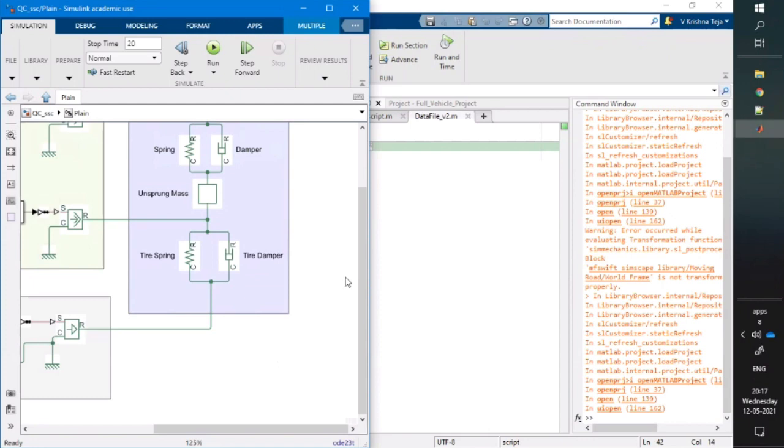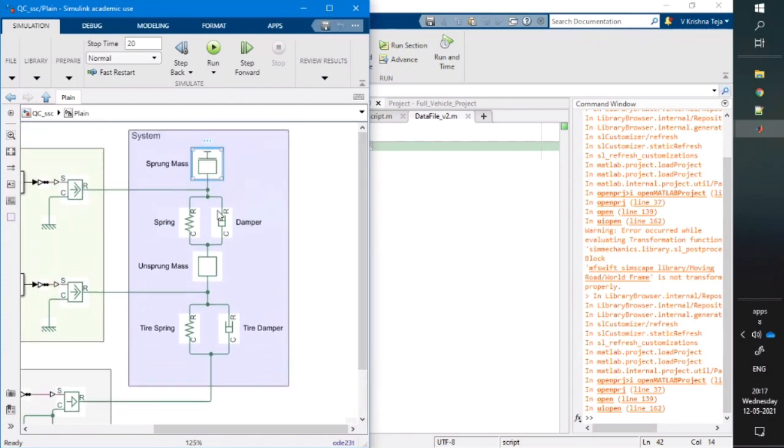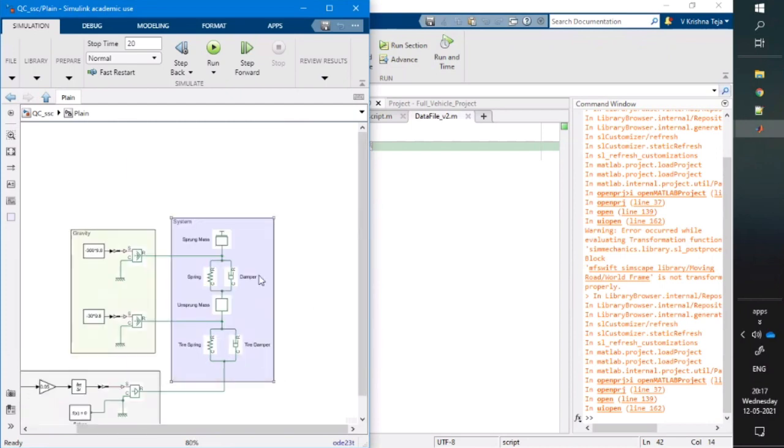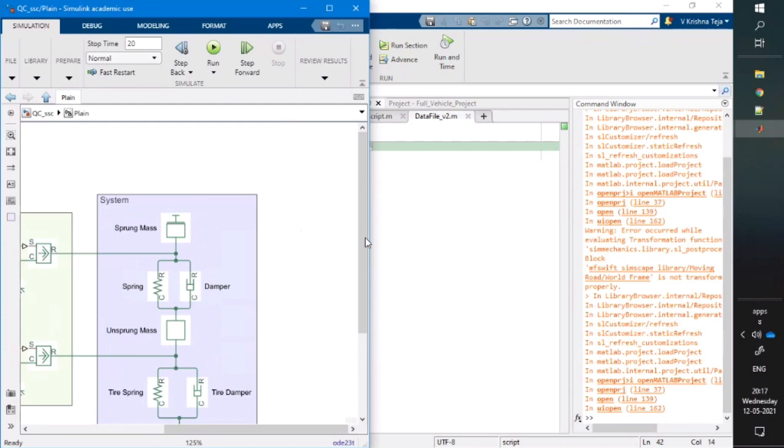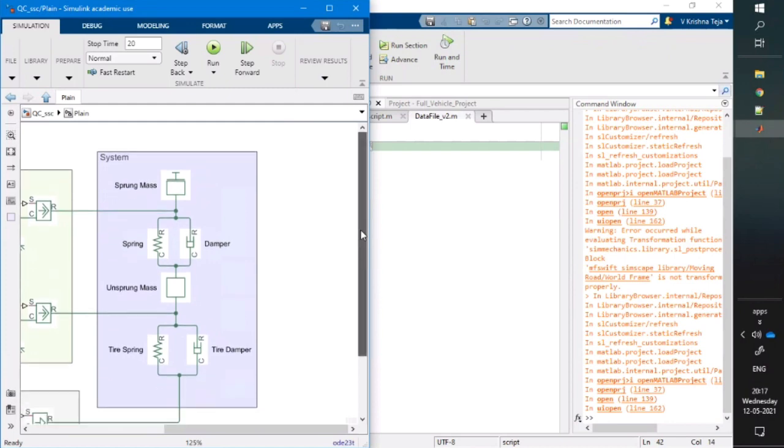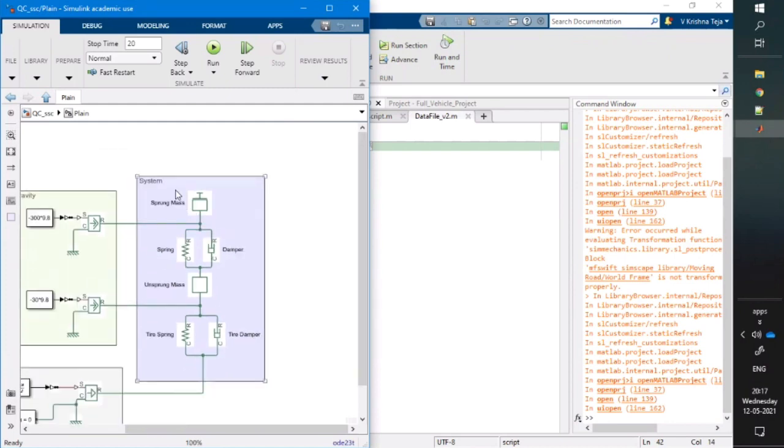It is simple. When you have two masses, two springs, and two dampers, things get quite complicated. You need 4 equations when you split up. That means you need to rederive all the equations. What if I say you need to add 2 more systems on top of it? Rederiving is a pain. With Simscape, it is as easy as our old friend, Control C, Control V.